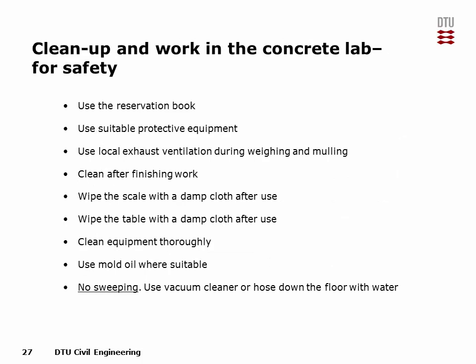In the concrete lab, it is important to comply with the following regulations. Always use the reservation book. Use suitable protective equipment. Use local exhaust ventilation during weighing and milling. Clean after finishing work. Wipe the scale and table with a damp cloth after use. Clean equipment thoroughly and use mold oil where suitable. Note that sweeping is not allowed. Instead, use a vacuum cleaner or hose down the floor with water.